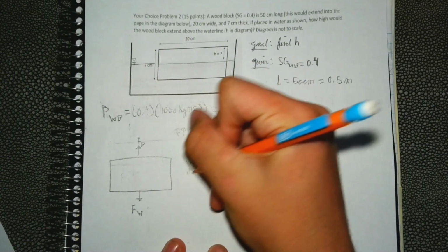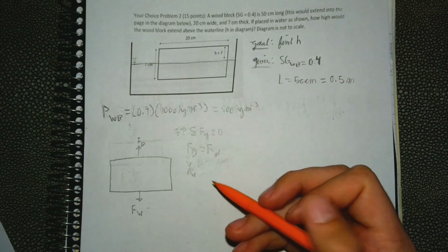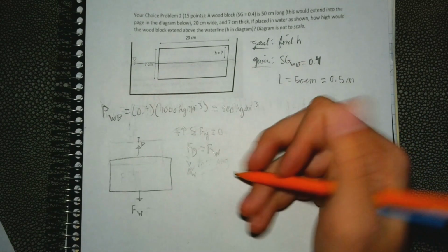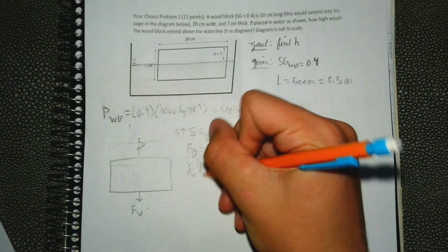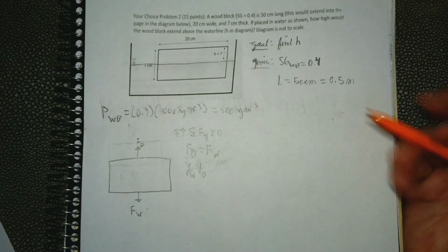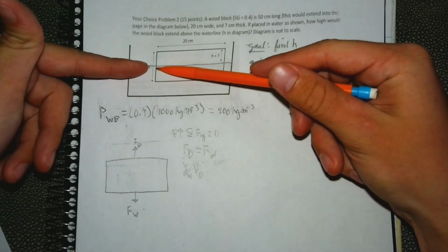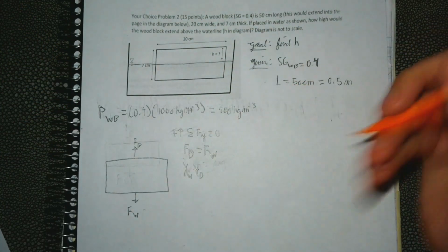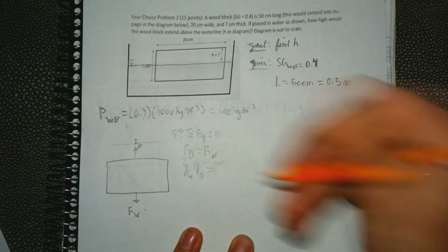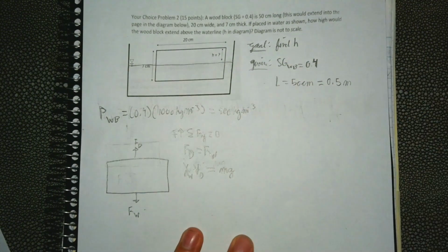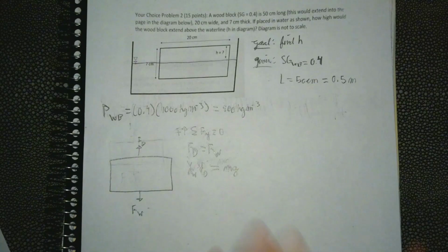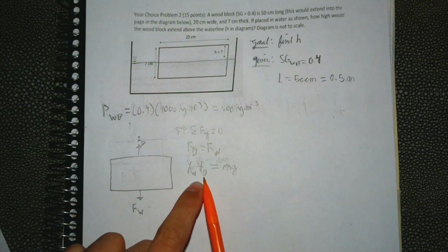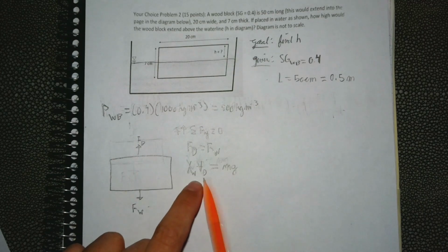The buoyancy force formula is the specific weight of the liquid it's floating in, in this case water, times the volume of the object that is displaced under the water. So the volume displaced in this case would just be under the water line, right? So the 7 centimeters minus h. And then the force of weight equation is mass times gravity. Alright, so we have to think about this. We're trying to find h, right? So where does the variable h lie in this? The answer is the height variable lies within the volume.